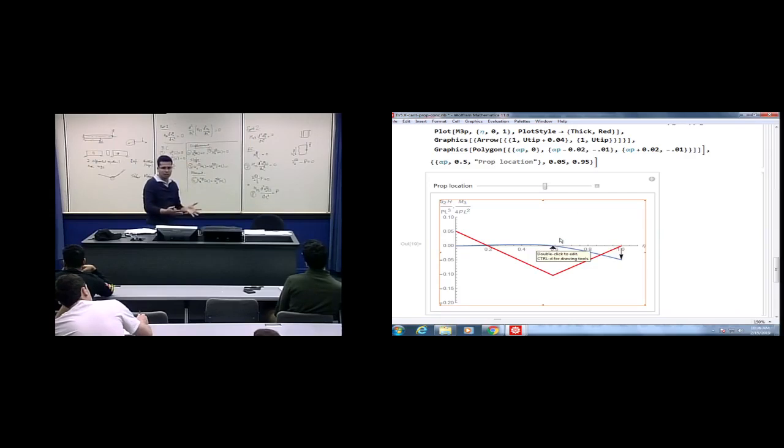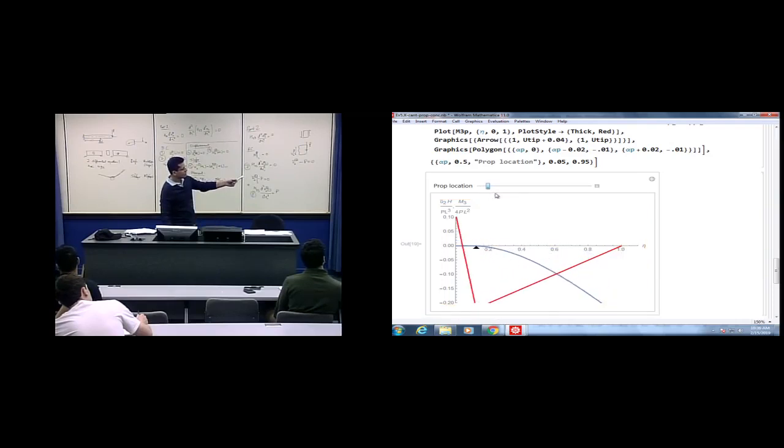So when you're designing something like this and you want to restrict the displacement caused by P, you will think of a method like this and put a support in the middle, right? By doing an analysis like this, you can see that if you put a support anywhere in this region, it's a significant reduction in displacement, right?